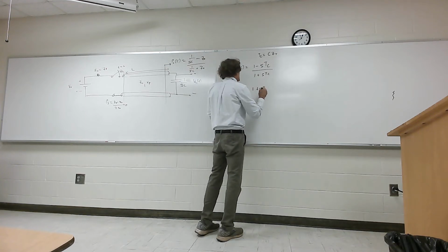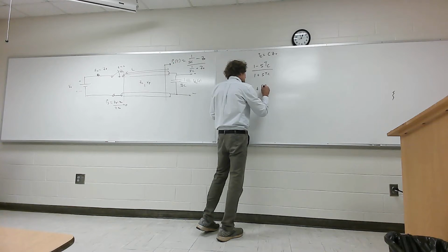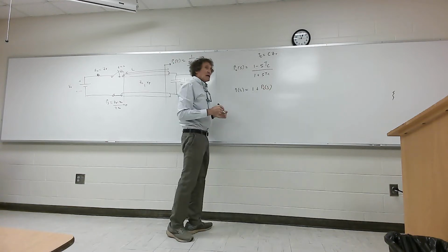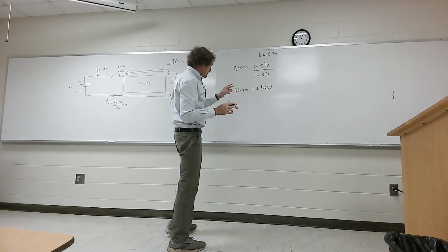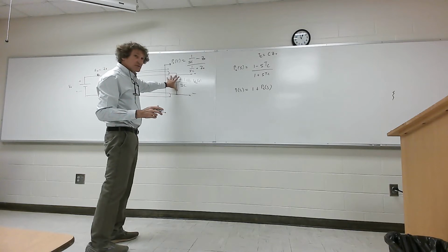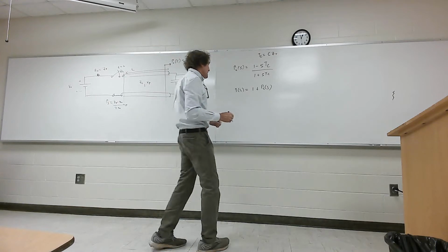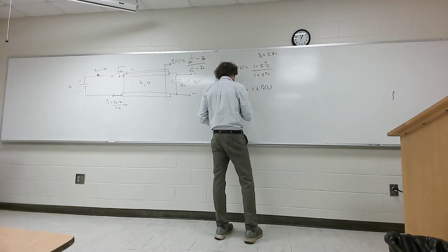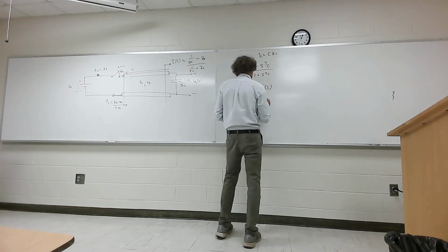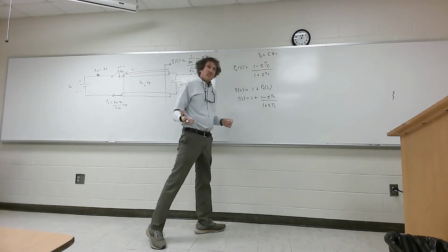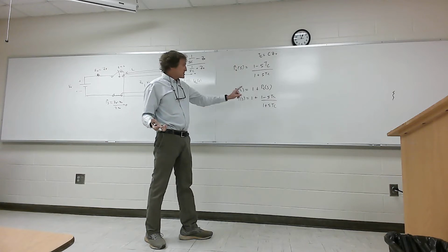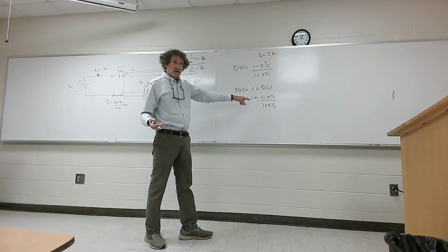And that's going to be 1 plus this gamma, the reflection coefficient of the load comes from that. And there's a reason I'm doing this, is because that's what I really care about. When I take this value, the transmission coefficient, times the actual voltage that impacts this, that is the voltage developed at the load. It accounts for reflection. So this is going to be equal to 1 plus, and then it's going to be 1 minus sTC over 1 plus sTC. You all see, the only thing I'm doing here is I'm literally taking the definition of that, putting it there, doing this, okay? Y'all with me?